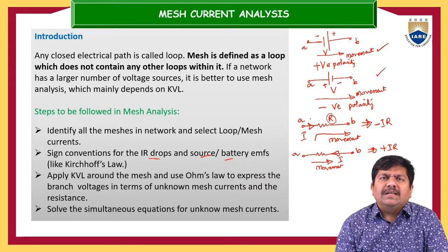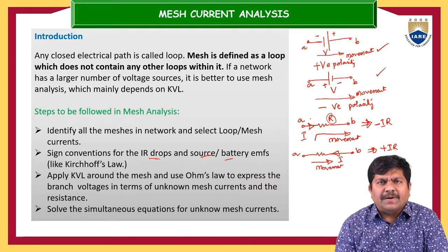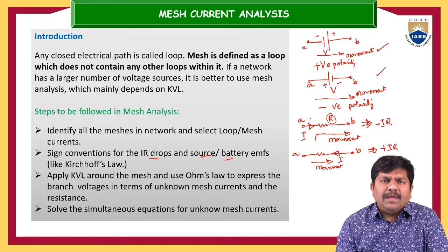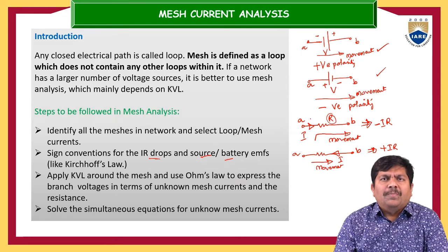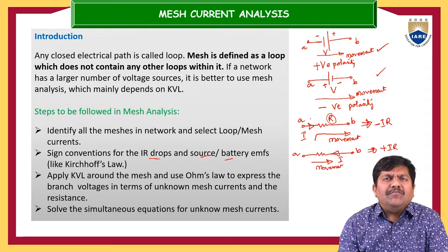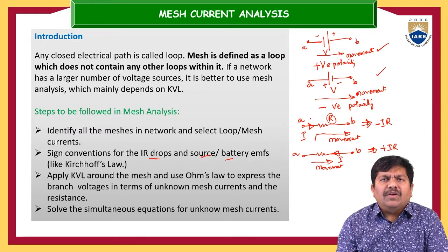You can make use of the basic electrical principles, associated theorems and statements to simplify the given electrical network by applying Kirchhoff voltage law or Ohm's law for the mesh or loop of interest. It will give mathematical equations, and you can simplify with the help of algebraic equations or matrices.